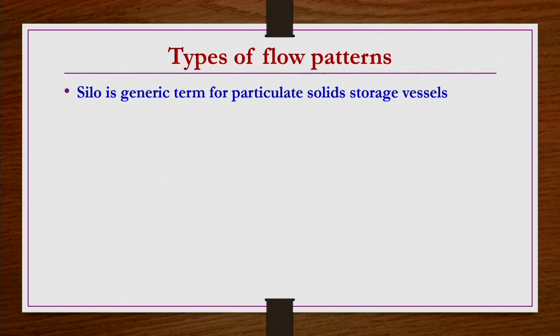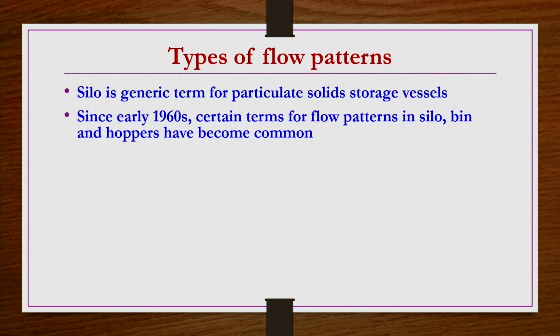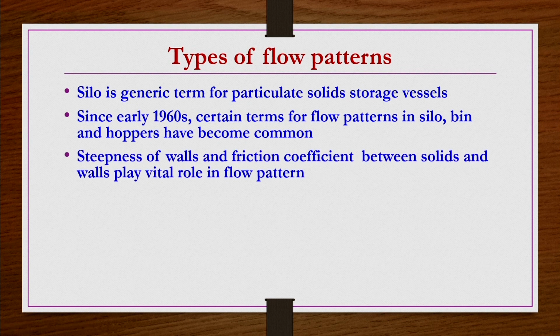However, before going to the flow patterns, in general, the silo is a generic term for a particular solid storage vessel, right. Since the early 1960s there have been several terms for flow patterns in silos, and bins and hoppers have become very common. So, we are going to see some of them now. As I mentioned, the steepness of walls and the friction coefficient between solids and the wall of the container or the bins is going to have a very important role in the type of flow pattern that is going to be developed while the solids are flowing out.